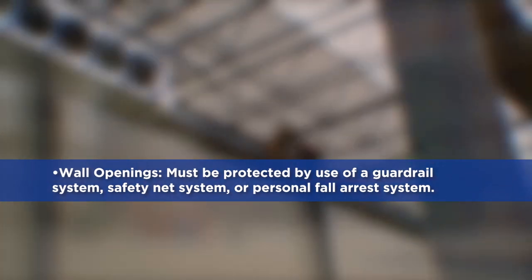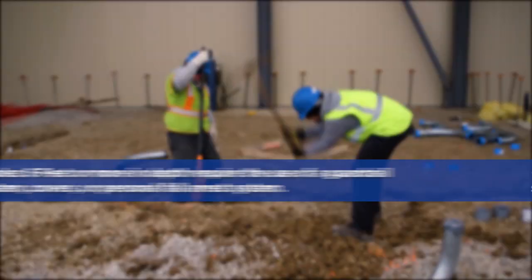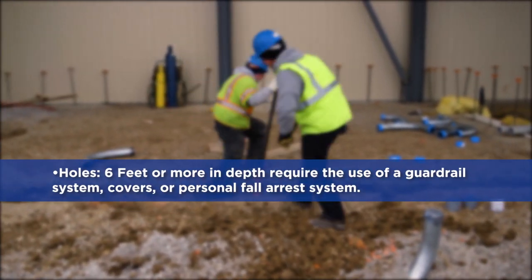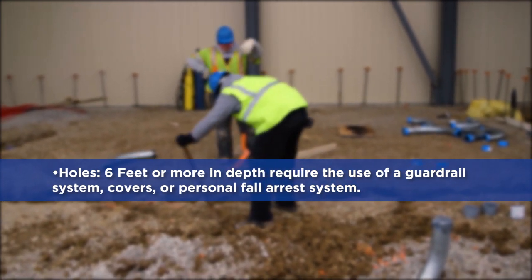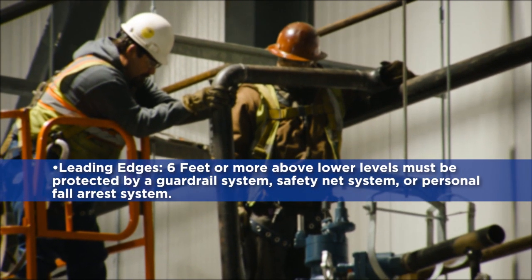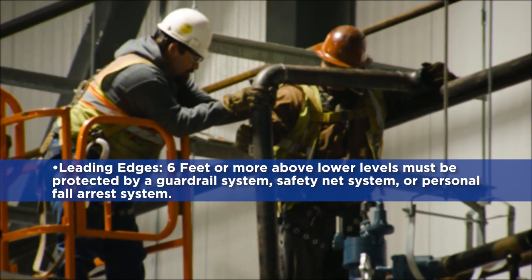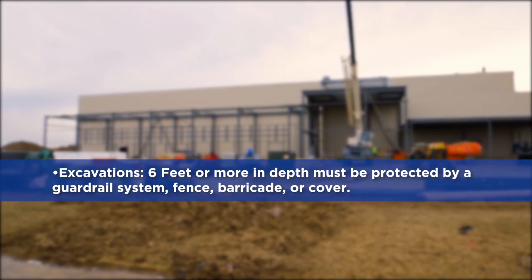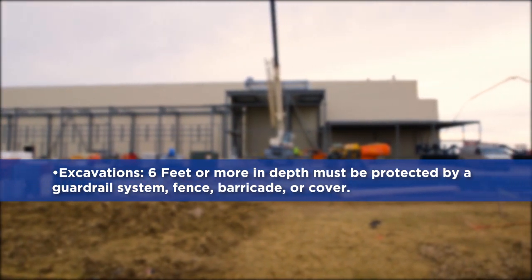Wall openings must be protected by use of a guardrail system, safety net system, or personal fall arrest system. Holes 6 feet or more in depth require the use of a guardrail system, covers, or personal fall arrest system. Leading edges 6 feet or more above lower levels must be protected by a guardrail system, safety net system, or personal fall arrest system. Excavations 6 feet or more in depth must be protected by a guardrail system, fence, barricade, or cover.